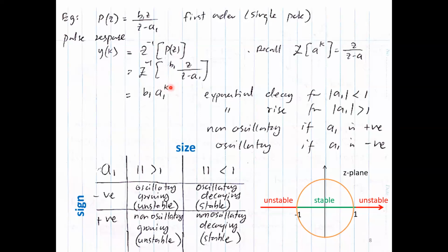My point is this K being 0, 1, 2, 3, 4, 5 doesn't change. And of course, at some point, this system has gone through a sampling process before you get over here. But if you just look at this one, you don't see any sampling information here, sampling interval or sampling frequency. What happened to that? Actually, the sampling is already included here in this A. This A is not only the system, it is system plus sampling together. So what you need to understand here is that when you have a plant, you can have an infinite number of discrete time models from the same system.